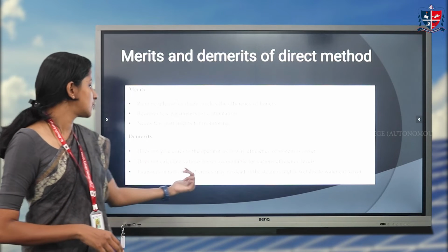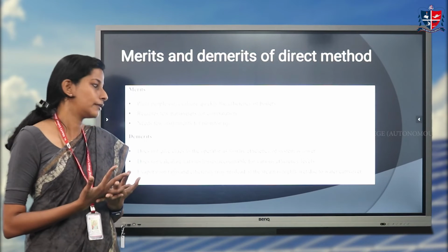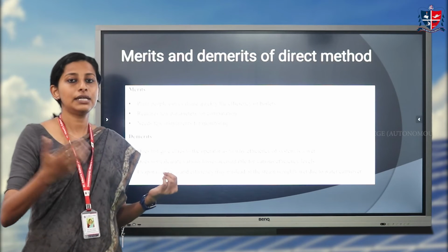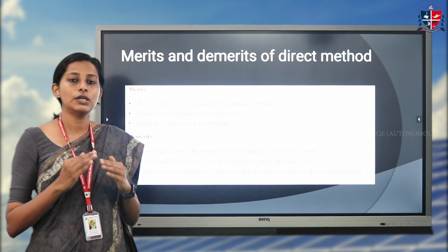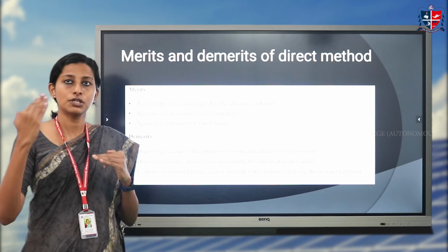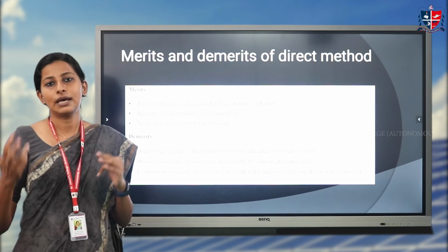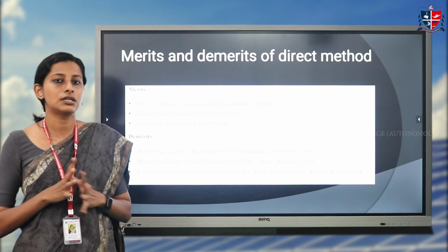Also, evaporation ratio and efficiency may mislead if the steam is highly wet due to water everywhere. So water carryover will happen, and due to the climatic conditions, when the ambient conditions change, evaporation ratio and efficiency values will change, because according to the atmospheric conditions, the steam generated may escape. That will depend upon the ambient conditions. So the readings are not accurate or exact because we are not considering the losses.